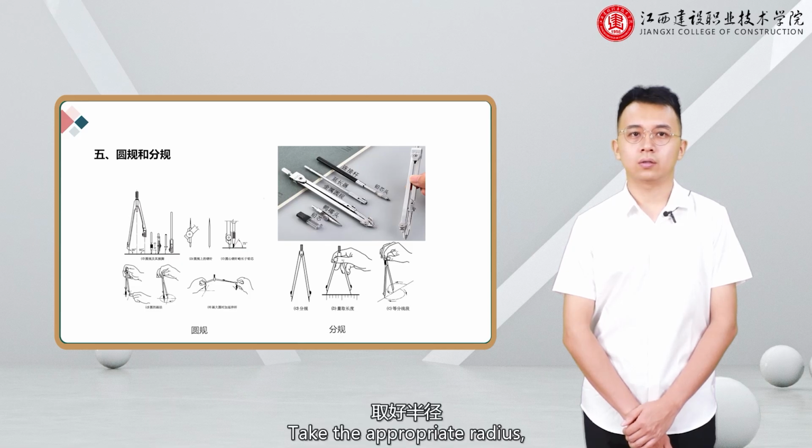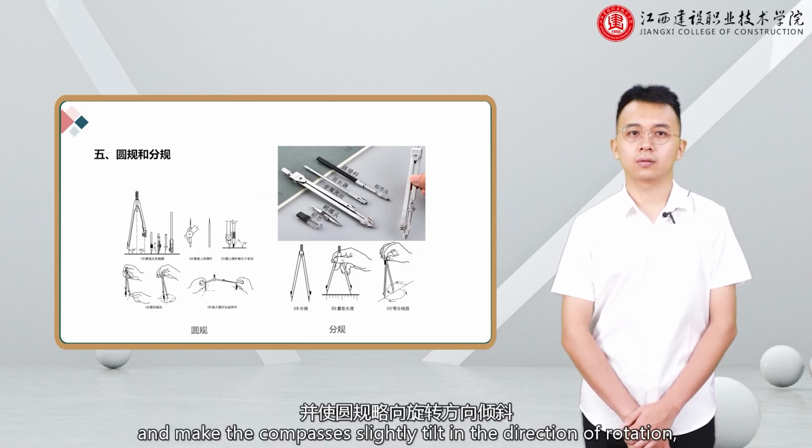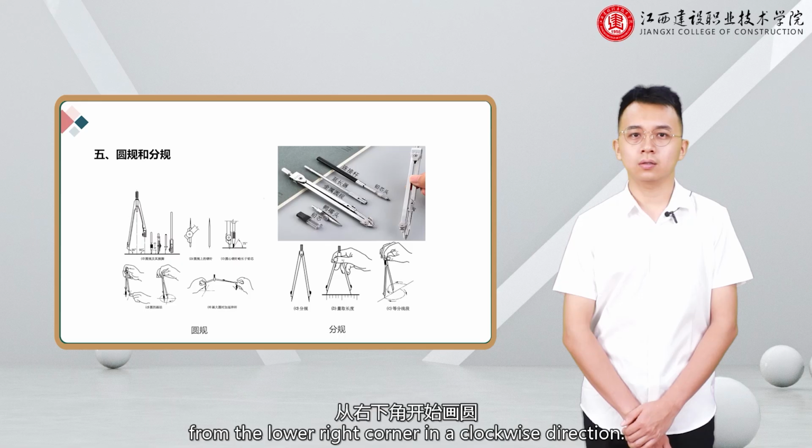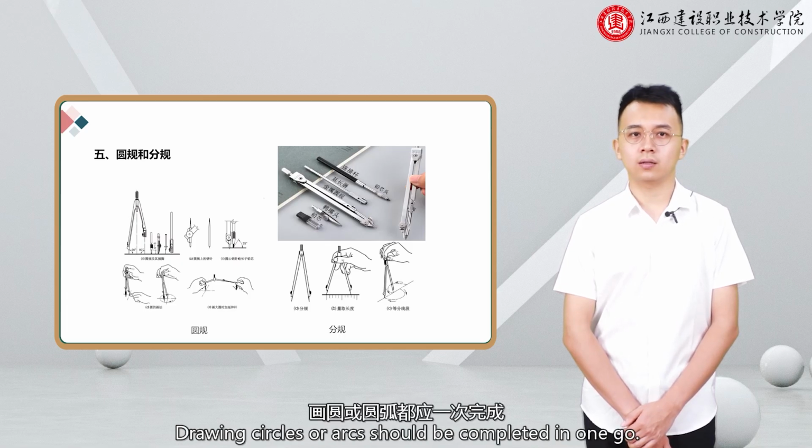Take the appropriate radius, align with the center of the circle, and make the compasses slightly tilt in the direction of rotation, and start drawing the circle from the lower right corner in a clockwise direction. Drawing circles or arcs should be completed in one go.